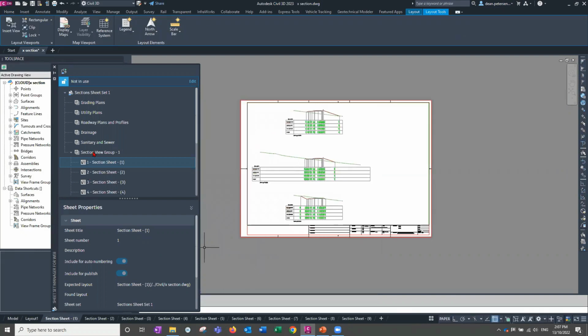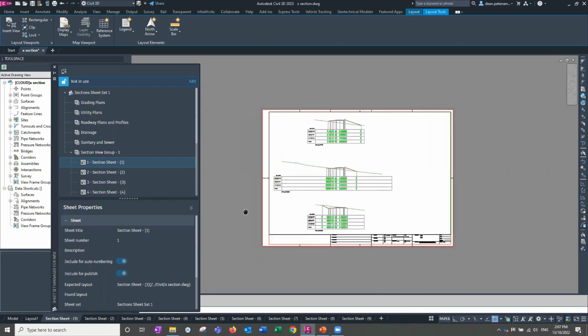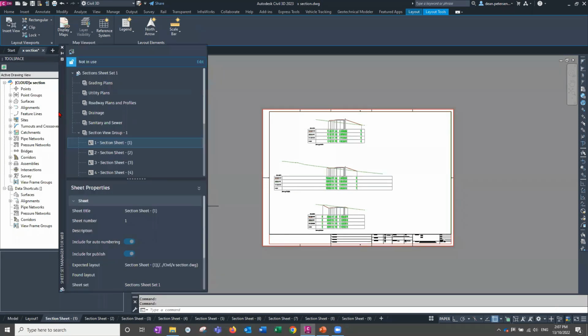Now it does. This was actually created by a drawing that was already up there, and it created the sheet set up there as well. And the actual wizard for creating those cross sections allowed me to access it and create it directly. So that's the new part. Civil 3D now works 100% with that. So that's the good part. That's now all functional. When this was known as BIM 360, I don't think they even had sheet sets at all up there. So now that's all functional.